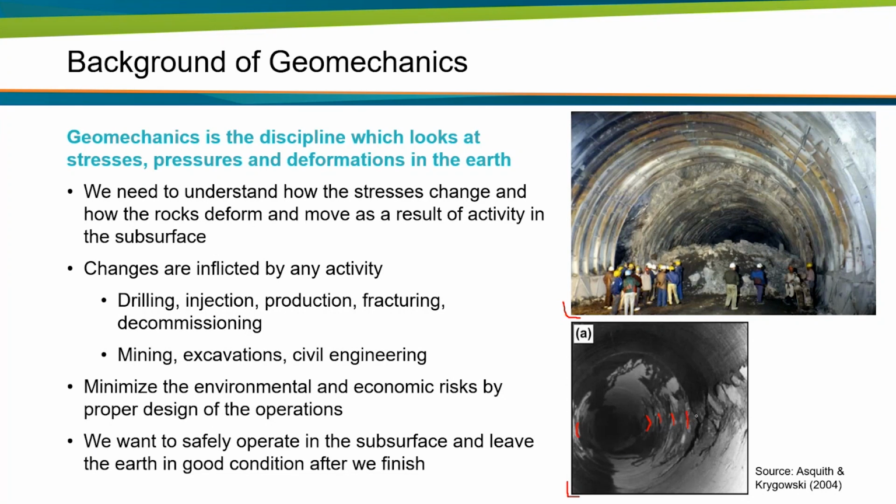These are breakouts, and when these breakouts happen and additional cavings and cuttings come into the wellbore, it will be more difficult to circulate the drilling mud through the wellbore, and it's more difficult to clean the wellbore. You might get stuck and it will take time to free yourself. And in the worst case, you need to go for a sidetrack, right?